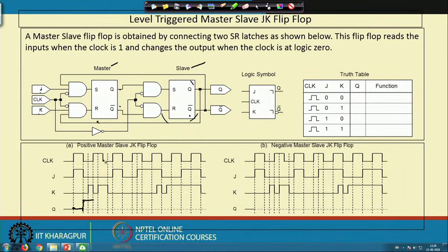So, at this clock boundary, when the clock signal becomes low, it will be making a transition to low and it will continue like this. So, this way depending upon the clock signal boundaries, whatever transition the master flip flop has made, the slave flip flop will make the transition when the clock signal becomes low. So, this is the master slave JK flip flop. So, you see that we need both the level high and level low situation of the clock for the output to get affected.